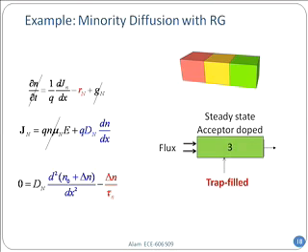The minority carrier recombination, delta n divided by tau n, right? That you remember. Now remember, the various approximations we did, that applies in various cases. Had it been high injection, what would have been this value? Delta n divided by tau sub n plus tau sub p. Remember, I was asking that question: how come in high injection the recombination looks smaller?